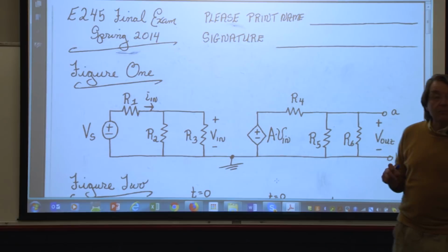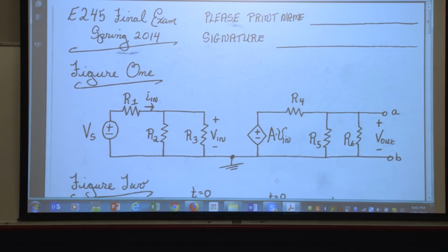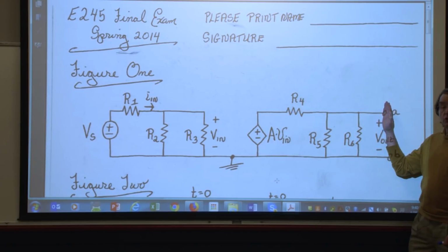Thank you. Now, Michael, I think you might have been also pointing out about I short circuit. Yeah, that's what I was talking about. Michael, forgive me. Now, be careful. If I put I short circuit here, what's the current through R5 and R6? Zero. So it's just going to be the current through R4. Right. Michael, you said it right. Forgive me for not following you. I short circuit here means there's no current through R5 and R6.